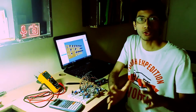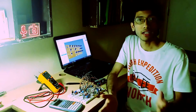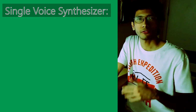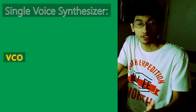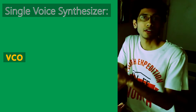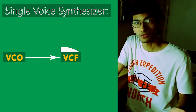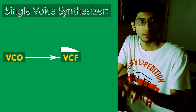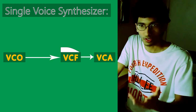So, just to ensure I don't fail, I plan to keep the design extremely simple. What I plan to build is a single voice synthesizer, and it will consist of five basic circuits. First is going to be a voltage controlled oscillator, which will be the main sound source of our synthesizer. That signal is going to go to a voltage controlled filter. This specific one will be a low pass filter to control the tone of our sound, followed by the filter is going to be the voltage controlled amplifier, which will control the amplitude of our signal.